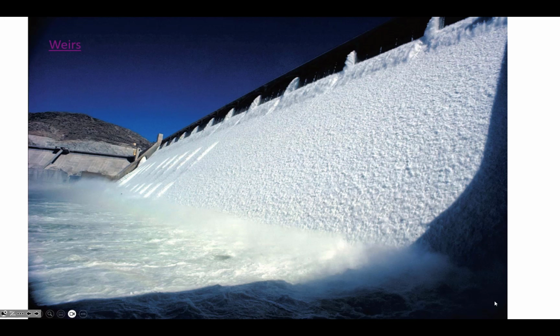And there are all these little particles which are settling downward in a clarifier, and they're so small that it's easy to disturb them. If the water that's going out is being removed at too high of a flow rate, it sucks these particles towards the outlet. And so you have to remove the water at a really low flow rate. You need to have a low velocity, that is. And so, in the video, it talked about how if you've got, this is like our circular clarifier tank, we're looking from a top view. This other one was a side view.